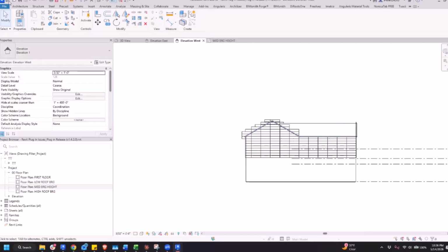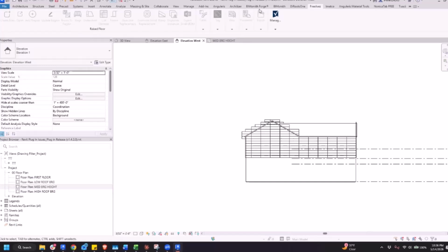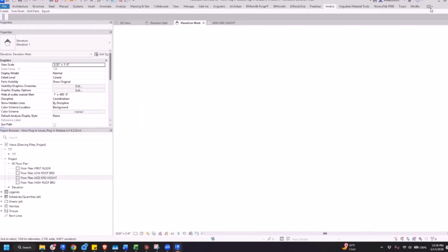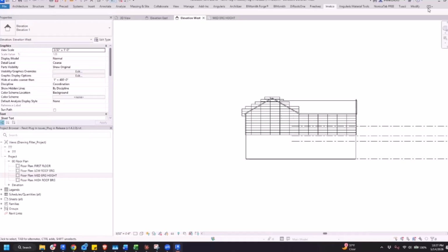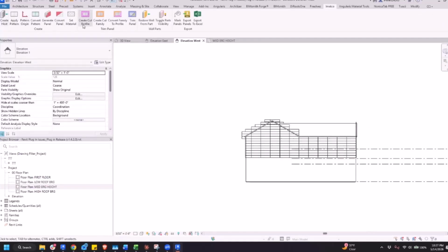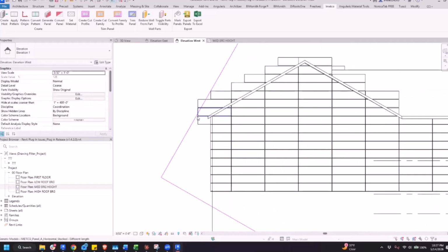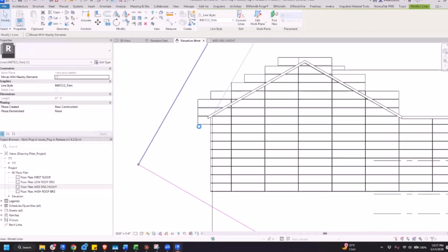Yeah. So the way that it would work is, if it's just a plain wall, I understand it, but usually the wall should have a door or window, and when you're creating the pattern for that wall, the pattern detects the boundaries of the window, and it will not create patterns inside it. So it shouldn't be part of this option. The only times you should use this tool is if it's not a window, if it's not a door, if it's only an opening, like just a cutout. That's the only time you'll need it. But a window and door doesn't need to use this tool. It does the other ones, uses the other ones.